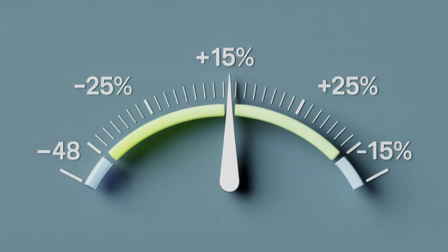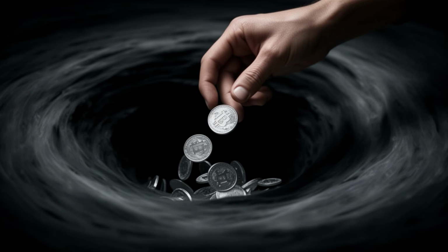Here is the critical detail that makes this failure mode so insidious. A MAF sensor degraded to this degree will often not trigger a check engine light. The ECU's fuel trim correction capability is typically plus or minus 25%, meaning it can compensate fully for the MAF error without ever setting a fault code. No check engine light, no fault code, just a fuel economy number that has drifted downward over thousands of miles so gradually that the driver has simply accepted it as normal aging.